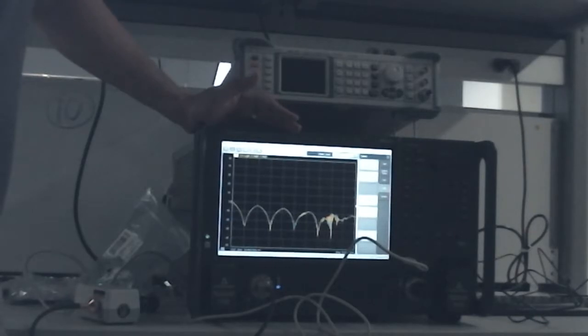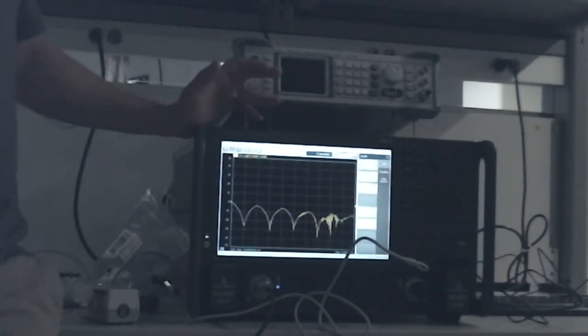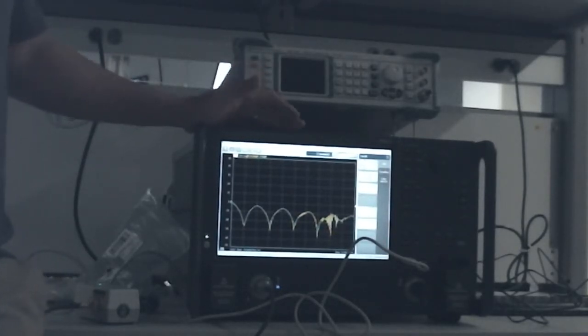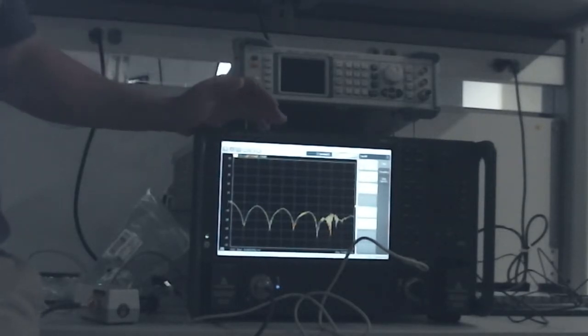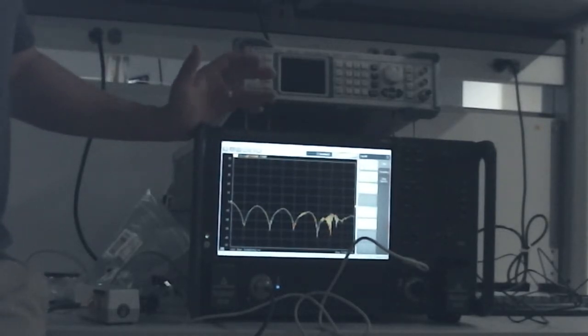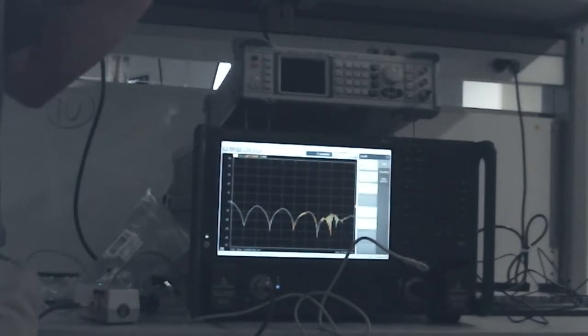So the other thing that you want to think about for your measurement is something called the IF bandwidth, right? If you look at a network analyzer architecture, it's effectively a heterodyne receiver, right? So you down convert into a narrow receiver. You have a source, and what you do is you sweep the LO and the source kind of in parallel, so that you do your swept frequency measurement.